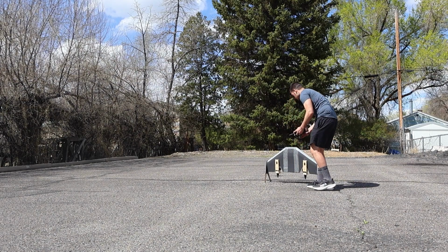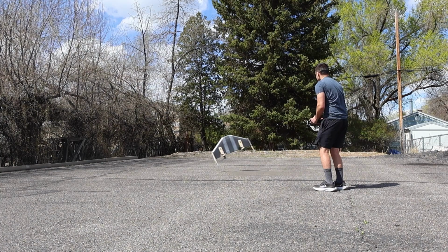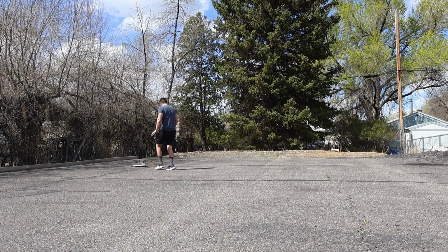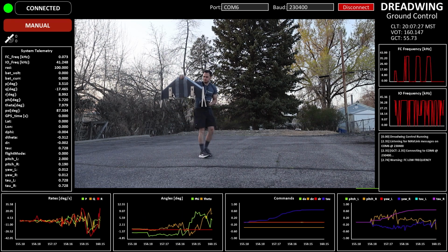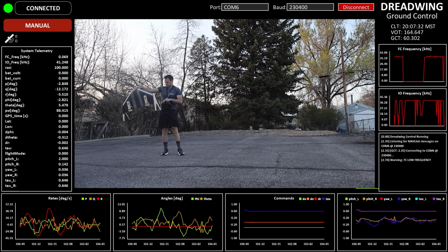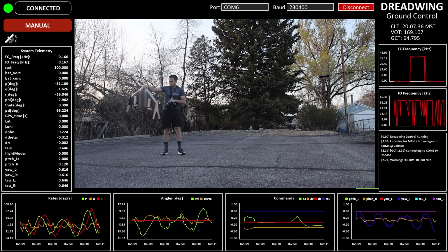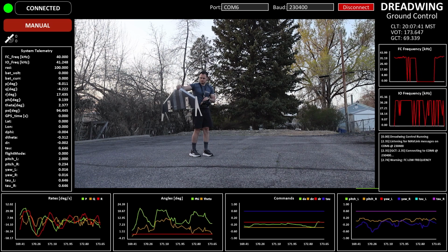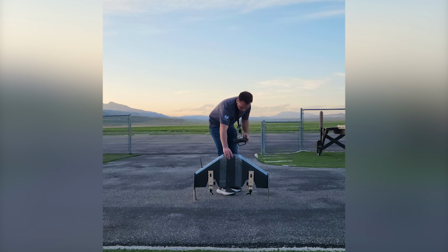Alright, now we can talk about actual flight tests. Tuning proved to be pretty difficult as accurate angle control was needed to even keep the vehicle in the air. Eventually the tuning gets better and I start to converge on better gains. Here I can get real-time telemetry data using my custom ground station, which helped in the tuning process. The tuning was still pretty difficult since I'm using a cascade PID controller, so isolating the axes was more difficult.